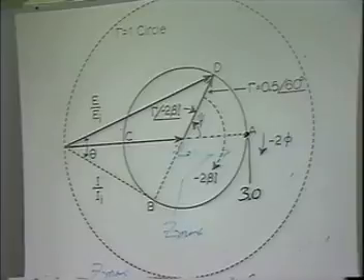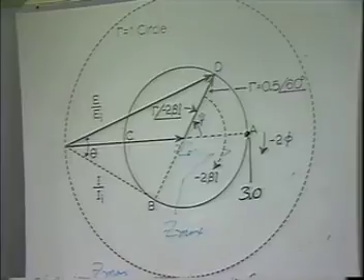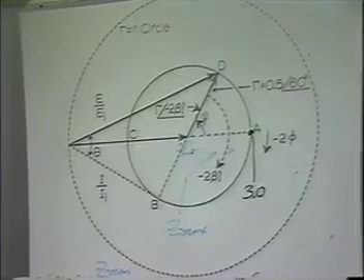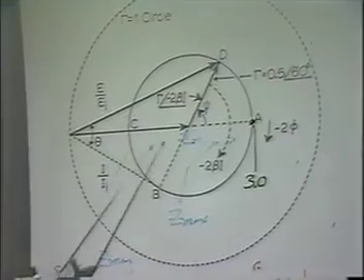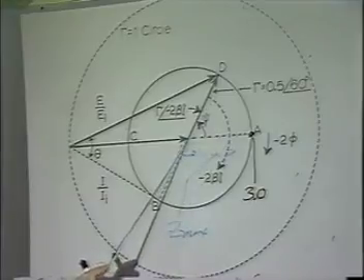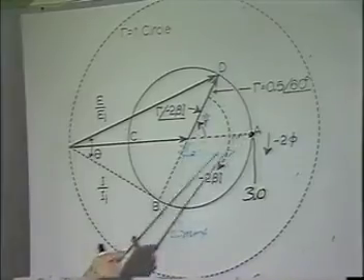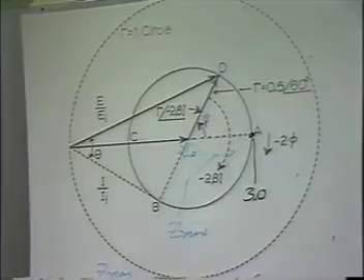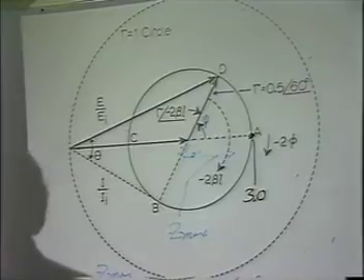Now, when you divide every impedance out there by Z0, you say that you have normalized. You've normalized everything to Z0. So on a normalized chart, what do you read on this axis here when you see those little numbers? 1 is at the center. What does it represent? Z max over Z0. When you read 3 out here, what does that say? 150 ohms divided by 50. In other words, the voltage standing wave ratio is 3.